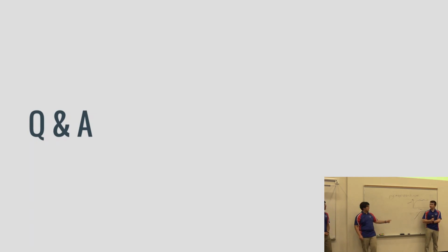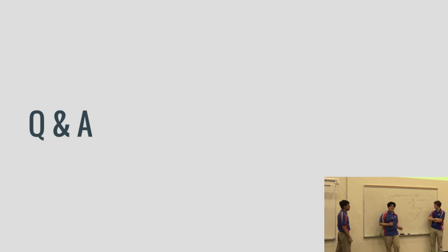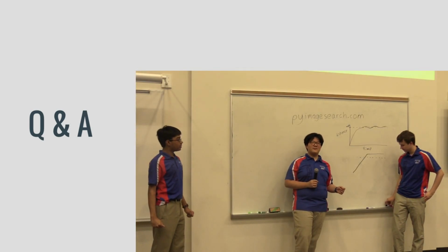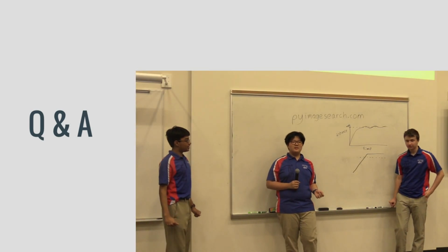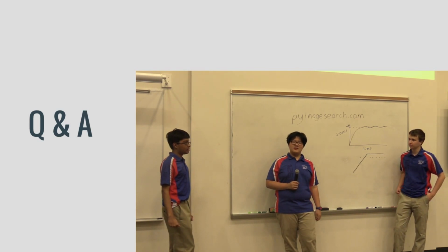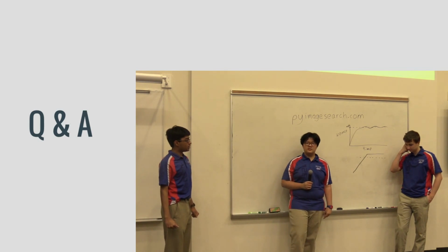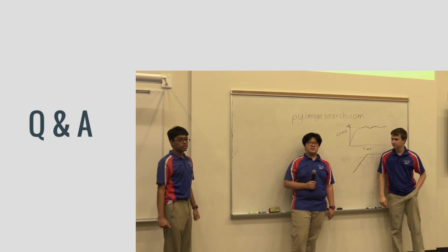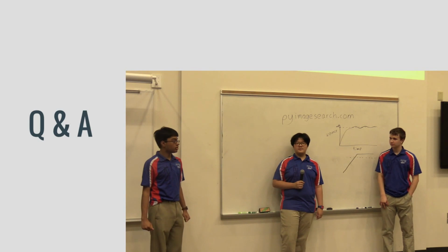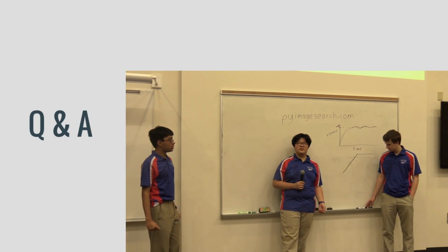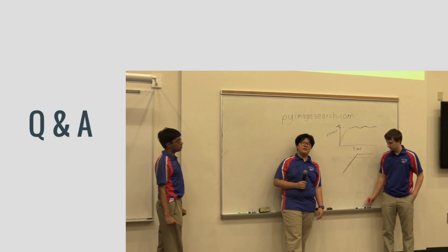Do you know if you can run TensorFlow on a Raspberry Pi? I like image processing and I'm into machine learning, so I can answer that. Yes, it can. It can actually run on a Raspberry Pi Zero, but not very fast. You can run it on a Raspberry Pi 3, but it's not going to be very fast. For machine learning and TensorFlow, you really need GPU power, and the Raspberry Pi is not GPU power at all. You would have to use something like an NVIDIA Tegra. That is just pure GPU power.